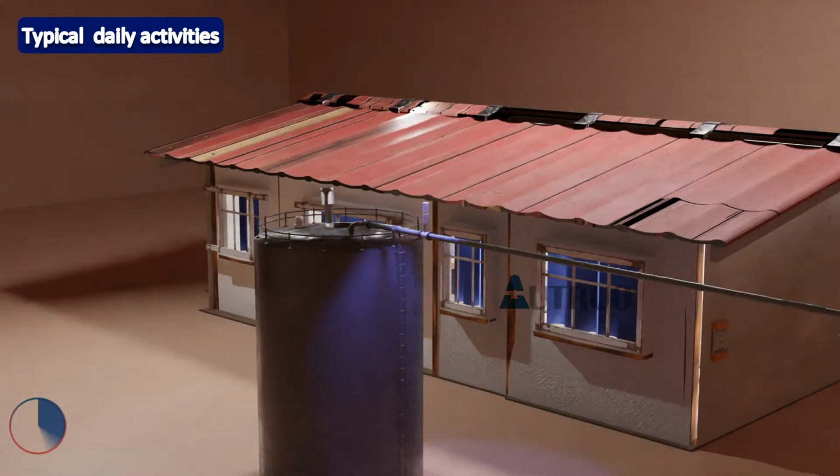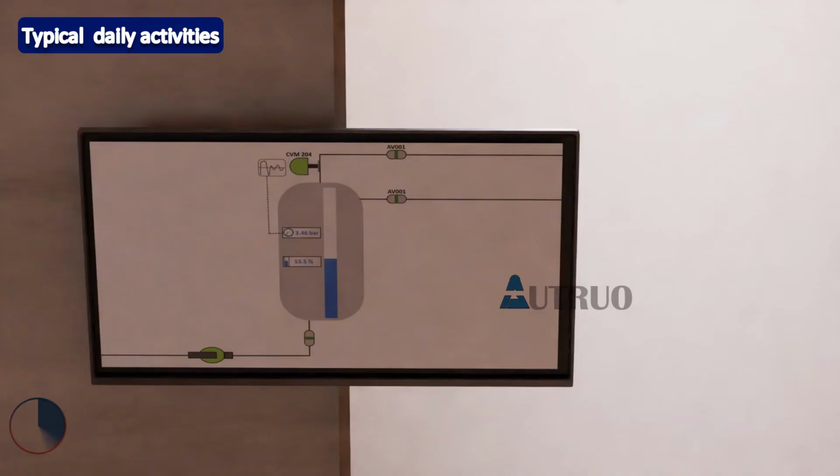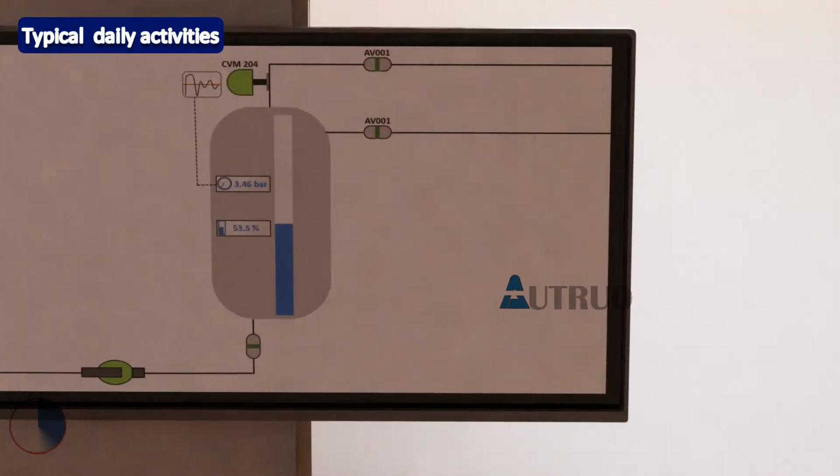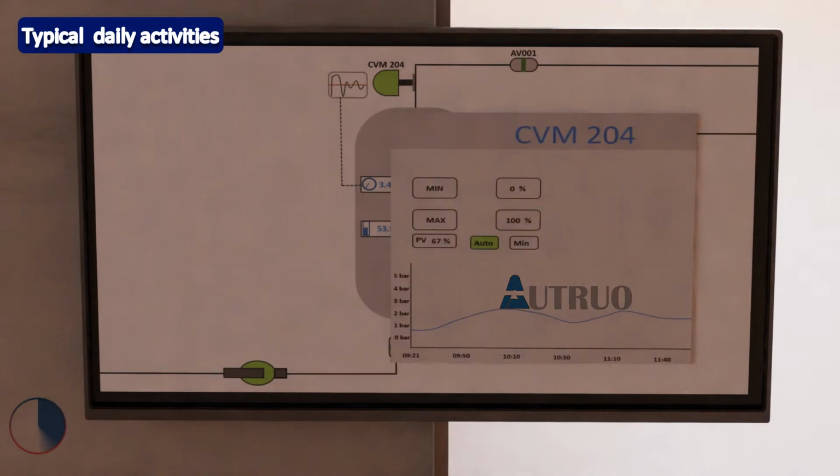Let's check the trends on the HMI, because the pressure transmitter will not give us the value we need at the moment. With the pressure trends, we will have a better understanding. From the trends, the pressure of the tank has not even exceeded 3 bar. This is far below the quick exhaust venting pressure, because as per the quick exhaust operating pressure, it is meant to be activated at 7 bar. So the pressure is still within its permissible range.